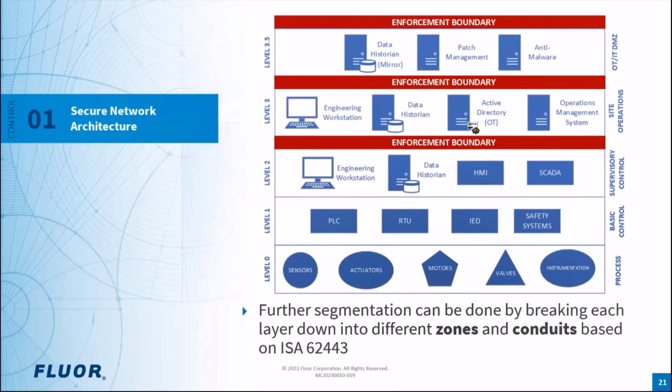So it's really about breaking the different systems into logical groupings into what they call zones. So if I have a petrochemical facility, and I take all of my safety systems, such as the safety instrumented systems, right? The fail-safe backup we have for that facility to shut down the plant in the event of an emergency, right? And we can take those and put them into a zone, and we can look at the different systems that it might communicate with. Those would be the conduits, right?